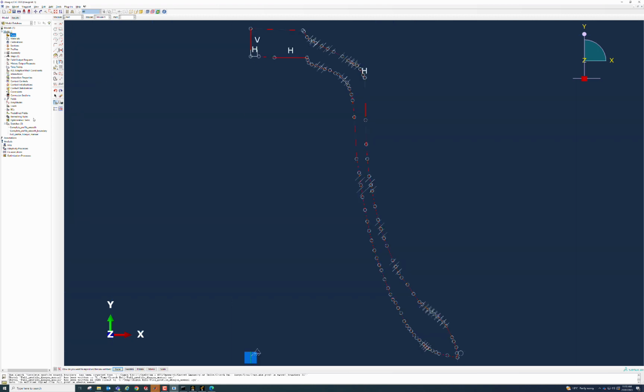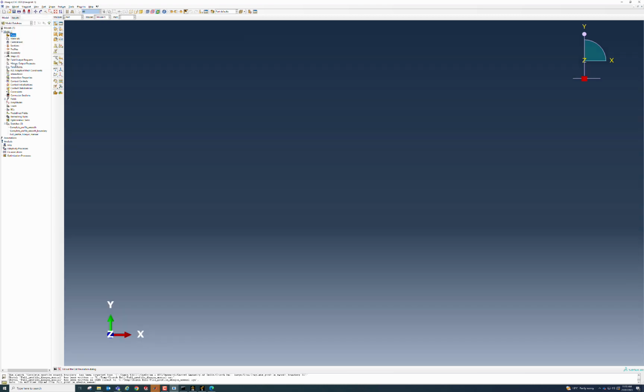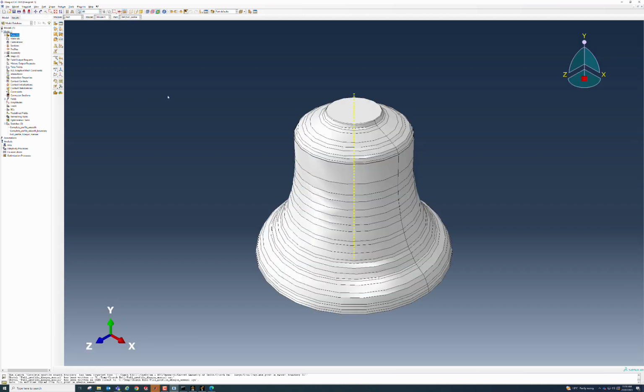Now when we import these sketches, it is worth noting that the unit system being used for the raw data here that defines the distances between the points is millimeters, so we will need to define our material property in millimeters when the time comes. I'm just having a look here to see some of the different points in this axisymmetric profile, and then we'll define to revolve that around 360 degrees, and you can see the result here, the solid model.